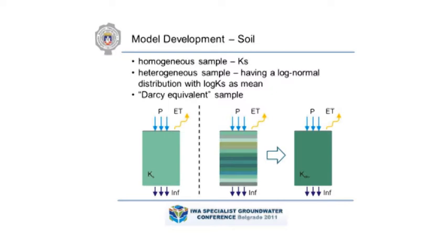However, knowing that the soil material is very heterogenic, which the field investigations have shown, we also observed, not just us, but most of the researchers, that the variations follow some pattern. Actually, the hydraulic conductivity and porosity follow a log normal distribution in space. In this type of analysis, those quantities are usually considered to be stationary, meaning that they do not change in time.